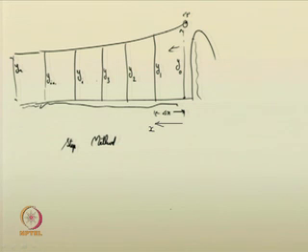So, the entire reach, as mentioned, is being discretized. Then from the beginning of the control section, where this depth is known, from that you are computing the other quantities, and then proceeding the computation in the left side. For this particular case, it is in the left side we are proceeding the computation.